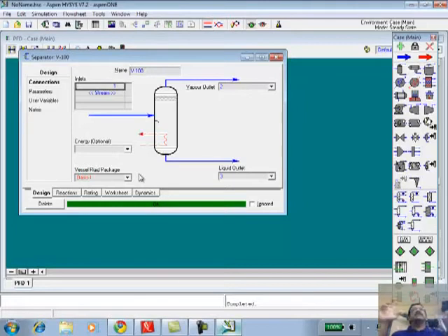Okay, and that's not easy to do because the way that we have set up the equations, we're solving for the vapor fraction or solving for the temperature or the pressure, and then calculating the composition. Think of it how you would do in a MATLAB situation. This is what you're going to do in your current assignment. You will hopefully reinforce all these ideas because I'm asking you to do the same thing in MATLAB and then in HYSYS and compare the two results. Okay, what would you do? You know root finding, you know bisection. Okay, so you know how to guess and verify whether the guess is right or not.